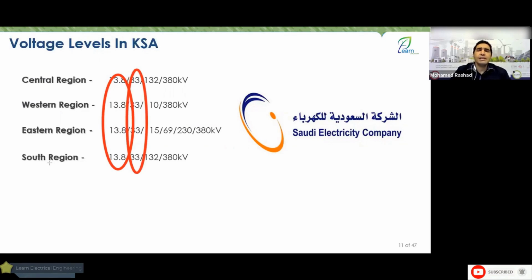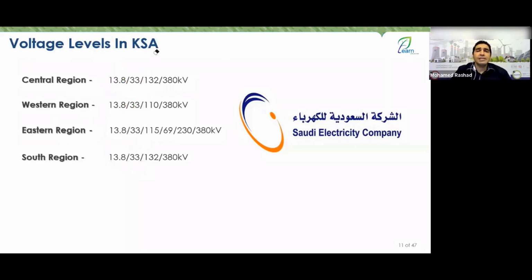Of course, you might ask, what about the 4th one? I'll tell you, it's the southern region. Nice, but if you then noticed, they had the idea that when you go to high voltage to transfer within the country, within the same region, from Riyadh to Dawadmi or elsewhere, they would raise it to high voltage in Riyadh at 132 kilovolts. In the western region, it was raised to 110 kilovolts. In the eastern region, it was raised to 115 kilovolts. And in the southern region, similar to the central region.